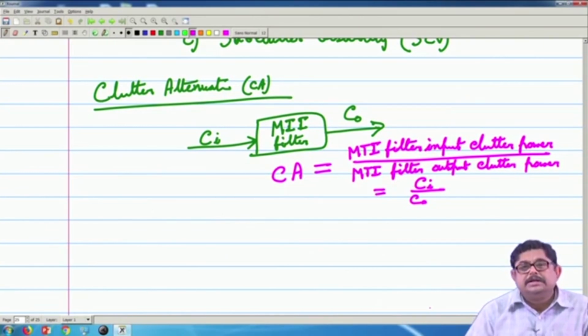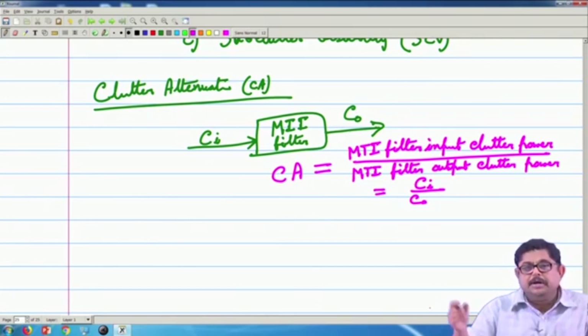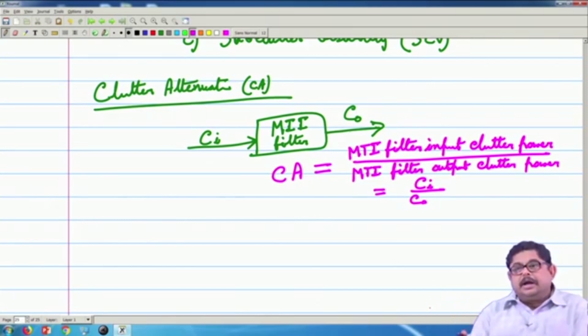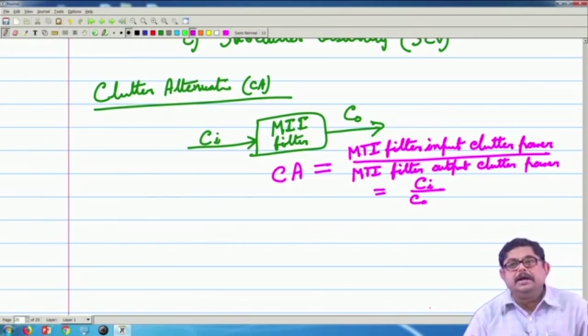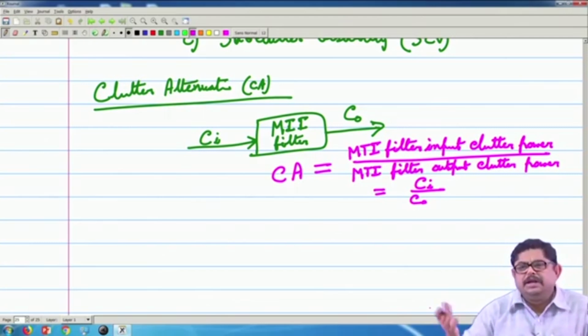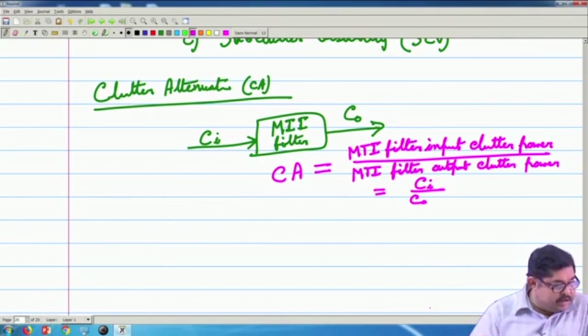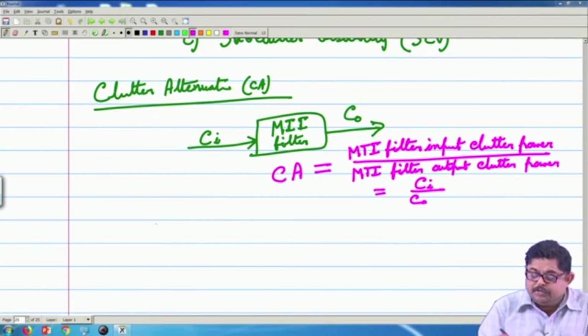Also, there is a central limit theorem which says that if there are no dominant scatterers and there are many scatterers of this clutter and no one is dominating, but there are many, usually 4 or 5 is sufficient, then whatever may be the individual clutter power spectrum, the overall will be Gaussian. So, with that knowledge we can say that if we model the clutter power spectrum,